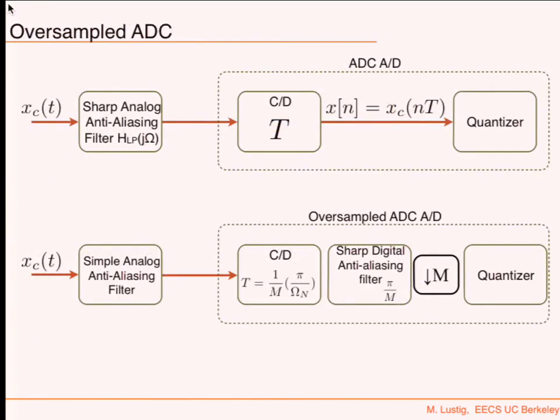So what we could do in order to mitigate that is not to sample at the Nyquist rate, but sample more than the Nyquist rate. Okay, let's try to give that. Have a faster A to D conversion. And what would that give us?